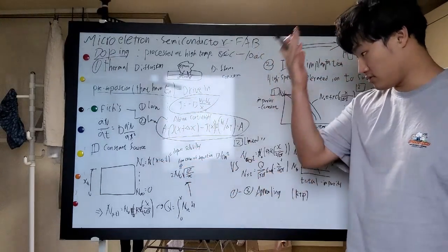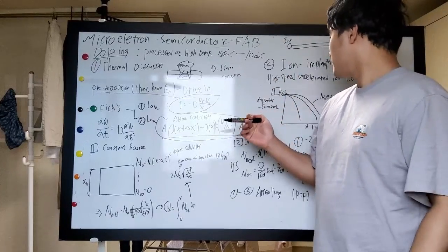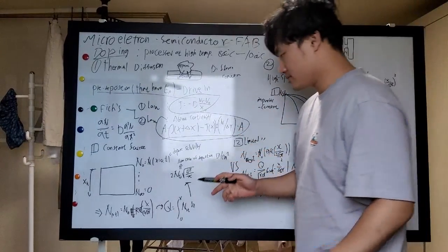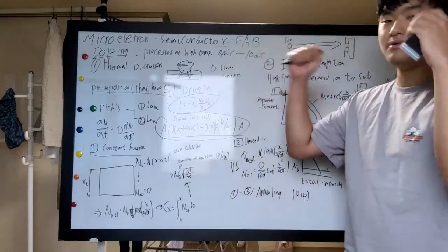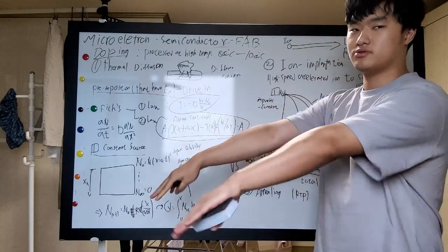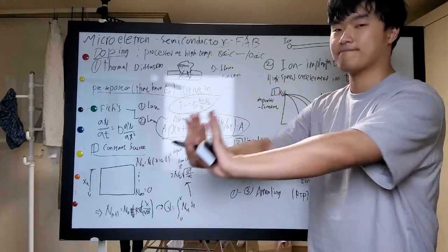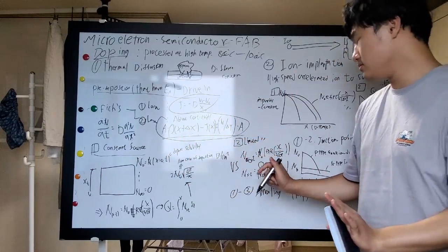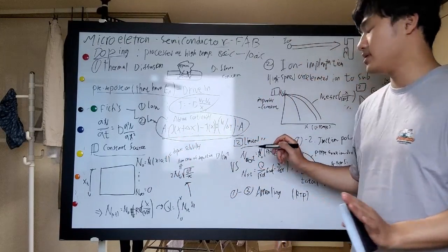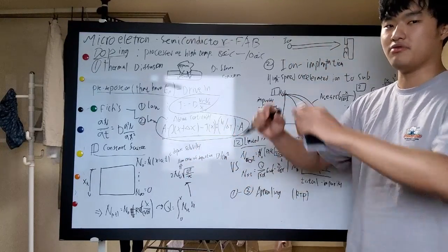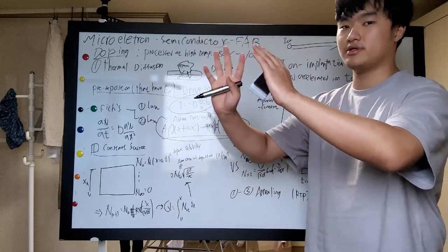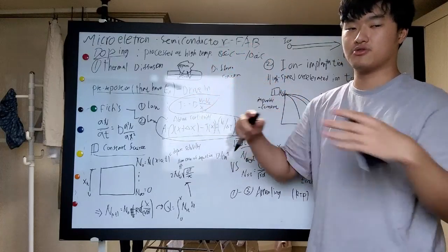So for the thermal doping, the first is the constant source. It means keeping the dopant source being injected inside. And secondly, the limited source. Limited source can be meant as just placing the material one time on the surface and it's done.